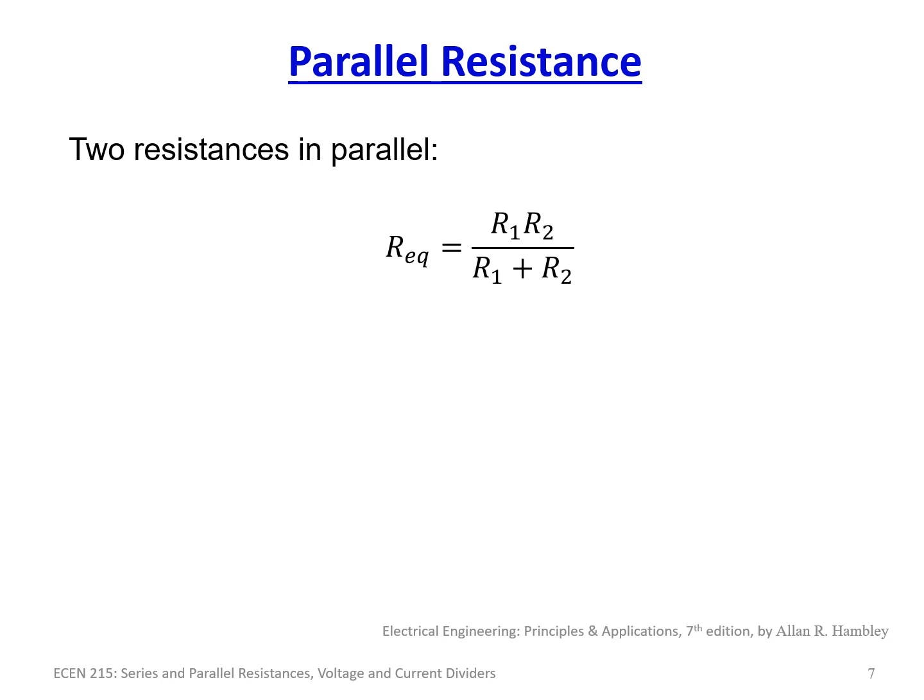So if you take the equation we just showed you a moment ago, you can actually work out this equation. It works out the same for two resistors. So you have R1 times R2 over R1 plus R2. In this case, we have just two resistors in parallel, R1 and R2, and this is the equivalent.